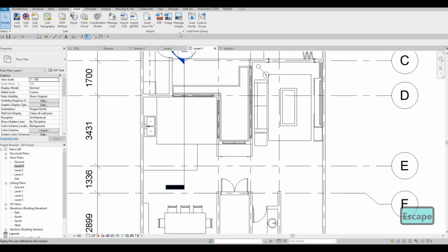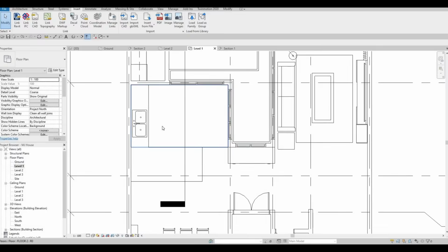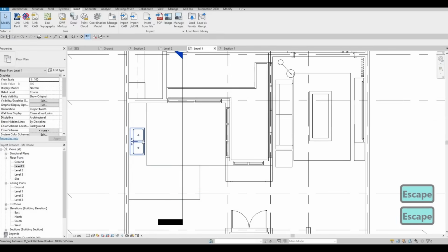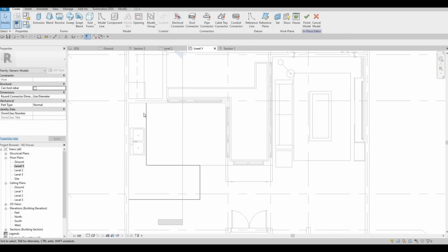So we'll probably need to add the fridge and then the casing, so that we know where to add the doors for the cabinets on the base. So now what we're gonna do is we're gonna select this again, edit in place. The reason that we need to edit in place again on the specific one that we created before is because we are gonna void it.